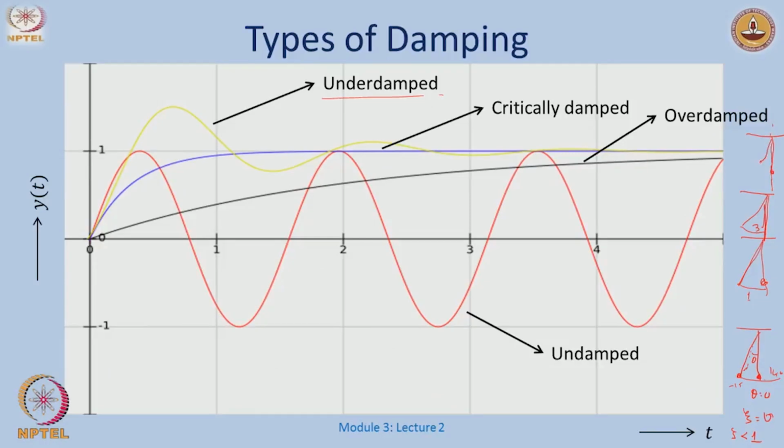There could also be situations where I start at theta 15, or minus 15 depending on the convention, and go very slow, very slow, and just stop here. It could take me 10 seconds. So, a few kinds of responses. Zeta equal to 0, I keep on oscillating. For some value of zeta less than 1, I am oscillating, but my oscillations die out before I reach the steady state position.